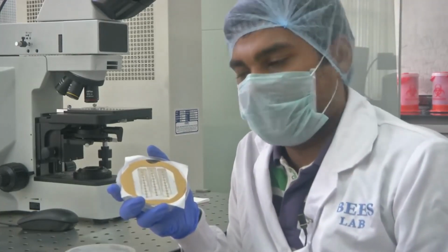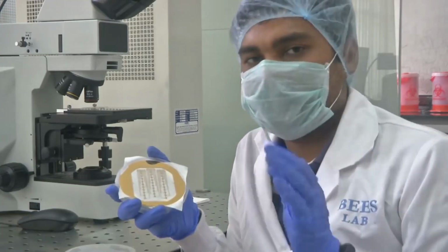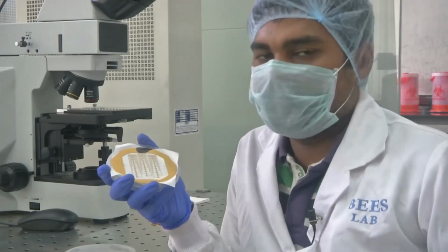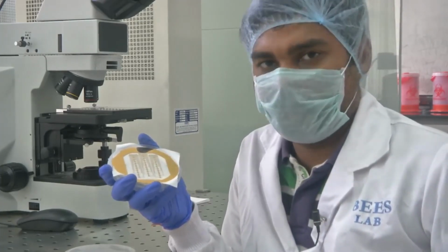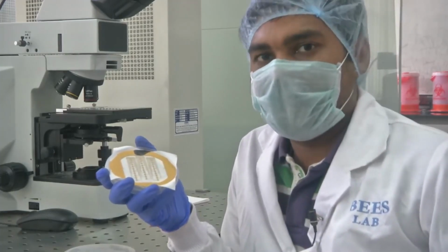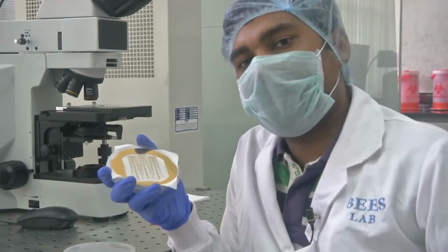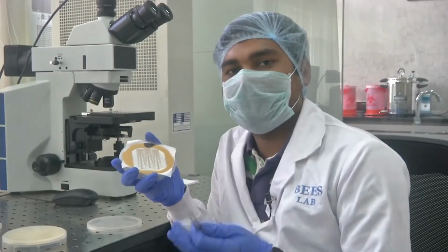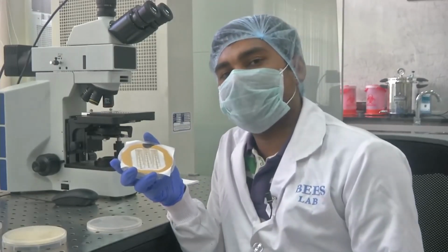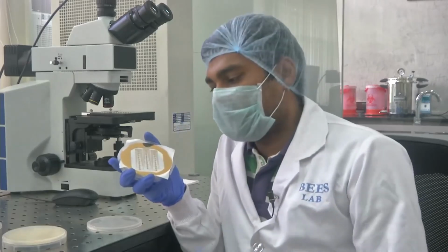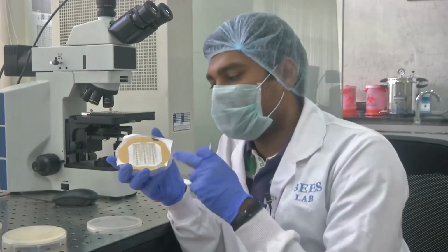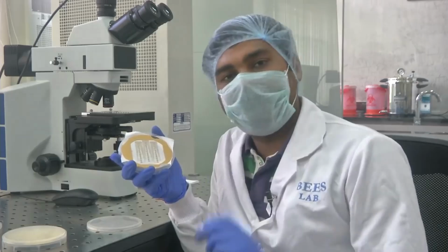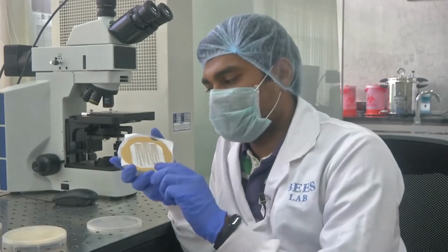Why has this happened? This is something to do with photolithography. Okay, so for photolithography we need a substrate, as you will know, deposited with some material. You will coat that substrate with the photoresist, and you need a mask with the pattern design on it, and that pattern will be transferred onto the substrate, correct? Now usually for a 4-inch substrate you will need to use a 4-inch mask. Likewise you can even use a 5-inch mask with a 4-inch area in the mask, but we have used a 3-inch mask because we make these designs also on 3-inch glass slides. So on a 4-inch wafer deposited with gold, we have used a 3-inch mask to pattern this.